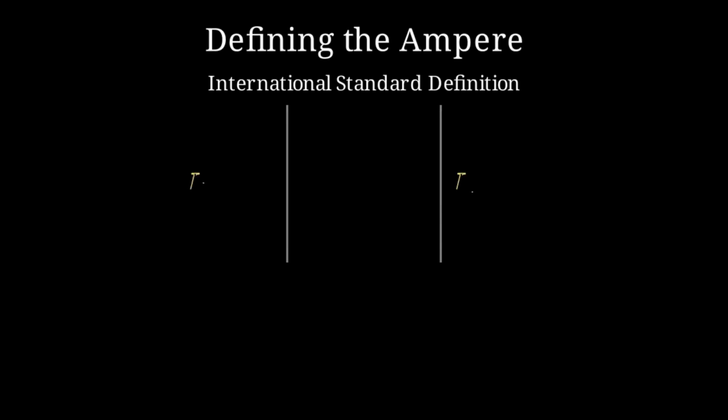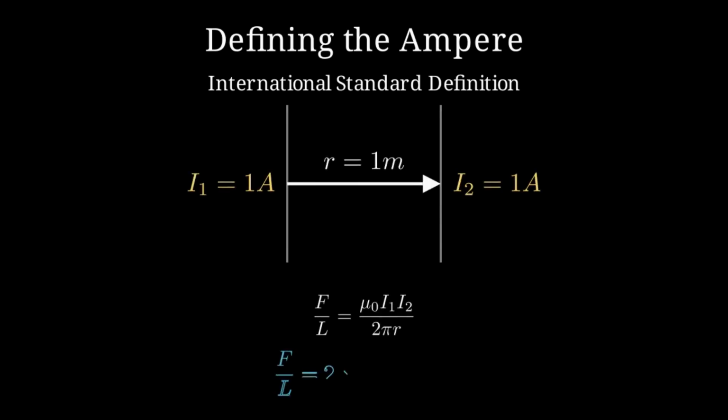The distance between wires is a critical factor. Because it is an inverse relationship, doubling the distance cuts the force in half. In high-voltage engineering, spacing is carefully calculated to prevent mechanical stress from these magnetic forces during power surges.